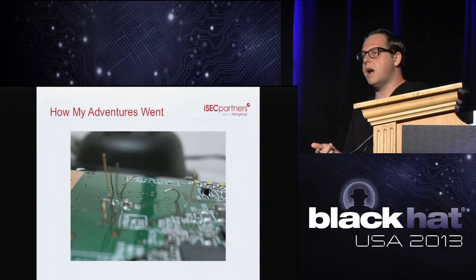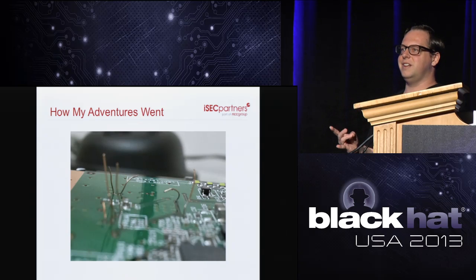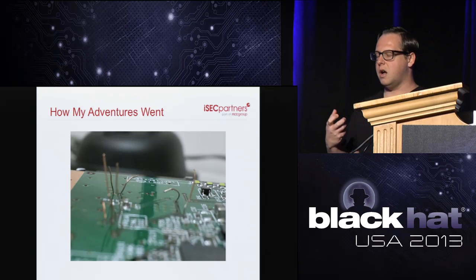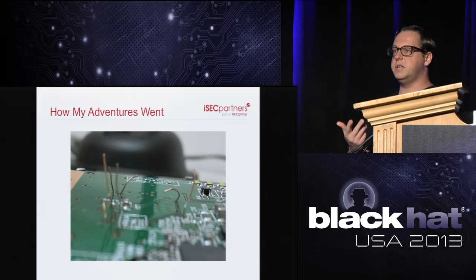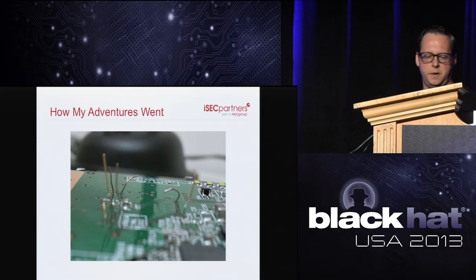Another great use for the epoxy, we can take these wires coming out. They're very delicate because these are very, very small things we need to be soldering. And trust me, take it from my experience, these are really easy to rip out with a logic analyzer. So there's tension on the logic analyzer probes. When you hook them in, if you're not careful, it could pull on those wires and potentially cause damage to the entire board. You have to throw the whole thing out. So the epoxy really helps to put that layer over there and protect this stuff while we're sniffing.